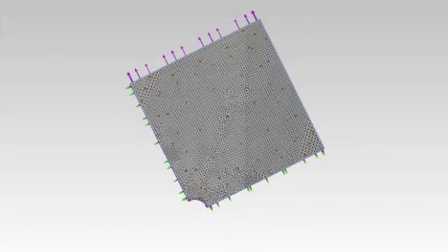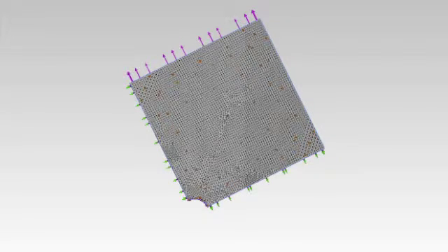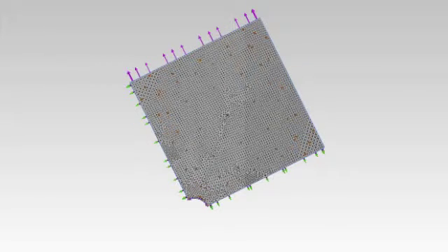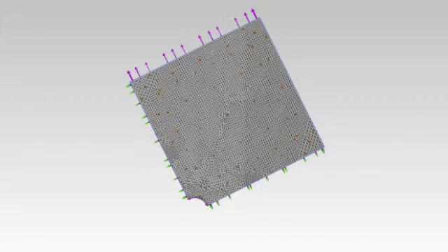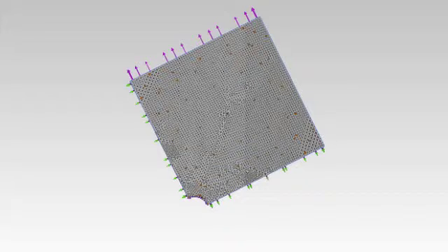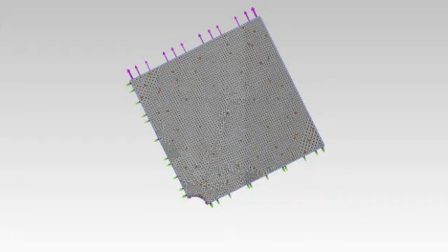With the use of SOLIDWORKS, we were able to analyze the stress concentrations in the model with a process called finite element analysis. In order to ensure the simulation was conducted under similar conditions to that of our experimental setup, when we created the model, we applied a symmetric constraint to the two cut edges and a roller constraint to the back of the plate in order to constrain out-of-plane motion of the plate. We then applied a 2,000-pound force to our polycarbonate plate and created a mesh, which enabled us to analyze the stress concentrations within the plate.